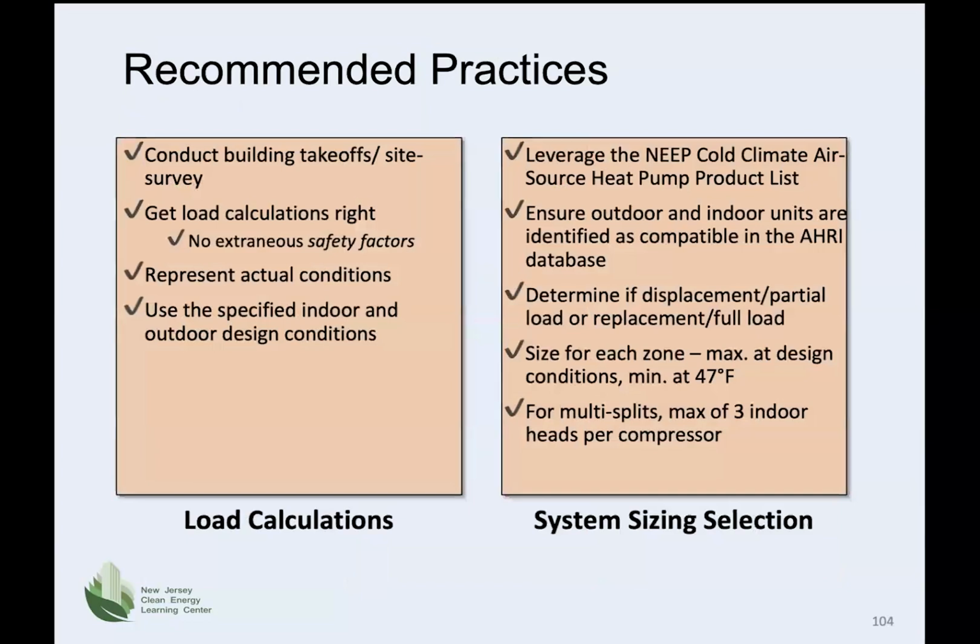These are the recommended practices for load calculations and for system sizing selection. They are to conduct a takeoff and then do the load calculations without adding any safety factors, because we know that the safety factors are already included in Manual J. And then you want to be sure that the actual conditions are reflected in the load calculation. And lastly, to use the specified indoor and outdoor design conditions for that particular geographic location. On the right are the sizing and selection considerations.